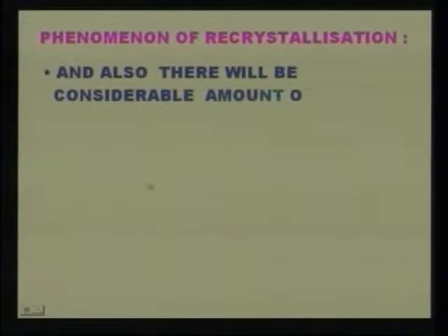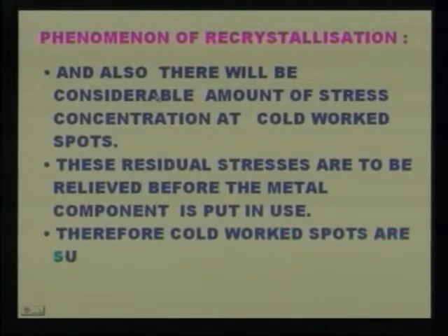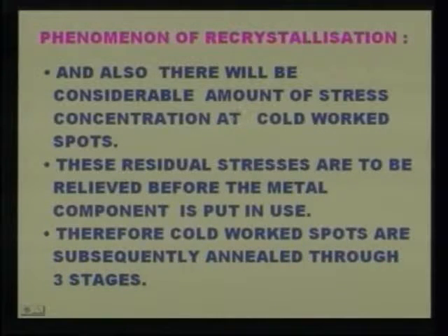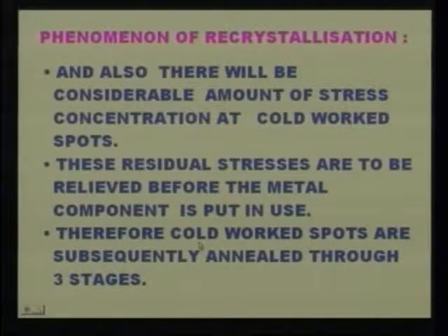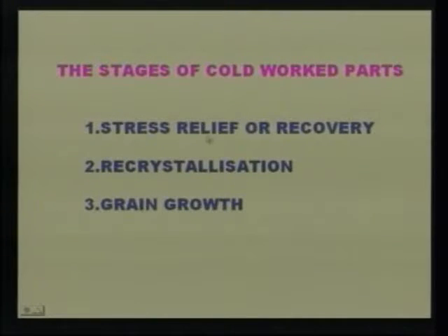Now you see some more points on recrystallization. There will also be a considerable amount of stress concentration at cold worked spots. Another point: these residual stresses are to be relieved before the metal component is put in use. Therefore, cold worked spots are subsequently annealed through 3 stages. Let us see what the stages are. These are the 3 stages: one is stress relief or recovery, the second stage is recrystallization, and the third stage is grain growth.